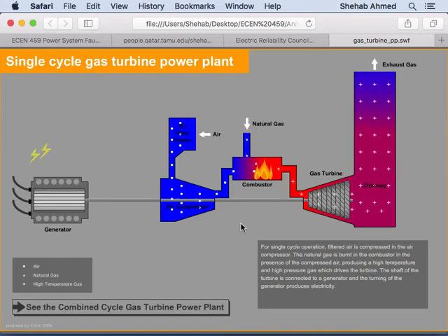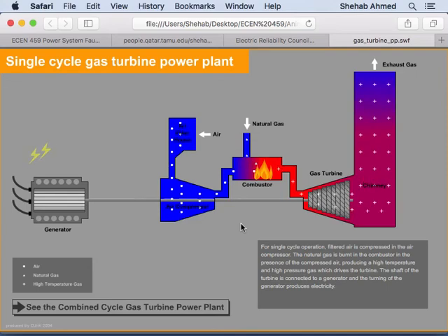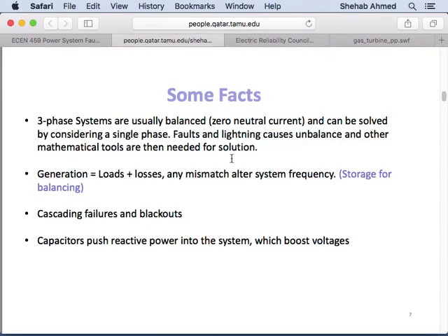And the people in the operating room sit down and they have to make sure this is all under control, right? So this is what's happening here. If it's not all under control, then what happens? Then you have some failures and blackouts, right? If the load is too much, for example, meaning Qatar Steel came online, the frequency deviated too much, and there was not enough generation to back that up. Then what happens? The generator's frequency changed, meaning it will fall out of synchronism with the network.